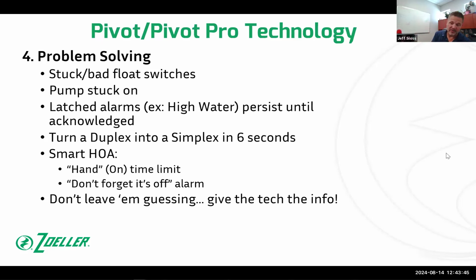And then the third thing you have to think about when you're putting in a panel like this, if you're using the Z control features, is that gateway, the little box. I don't know if you noticed it on the inside of the door of my panel, that's the piece that has the Wi-Fi chip in it. That has to be within the Wi-Fi range of your router. So if your panel's not going to live its life within the Wi-Fi range, that little gateway has to. So you may have to run a Cat5 cable between where the panel lives and where the gateway needs to live. And of course, you do not want to run a data cable inside of a conduit that has power. So those are things you have to think about ahead of time.